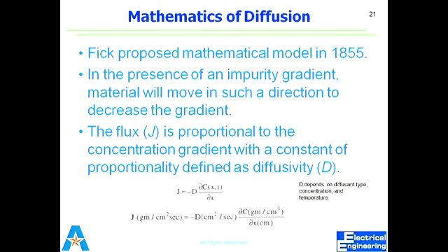In pre-deposition, the surface concentration is always constant. It's constant, which means that depending upon the time, if this is T1, this is T2, and this is T3, then T3 is greater than T2, which is greater than T1. So the higher the time, the greater the depth, but the surface concentration is constant, because you have an unlimited source, not unlimited surface concentration. This is constant, not unlimited.